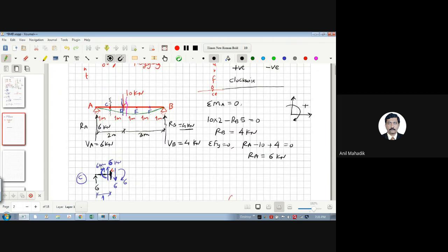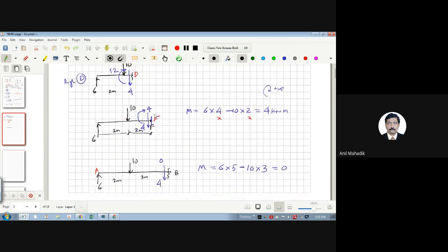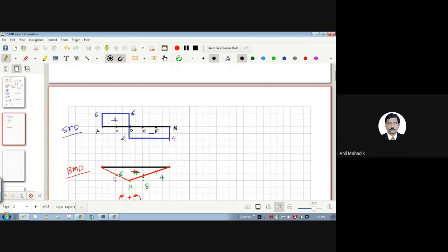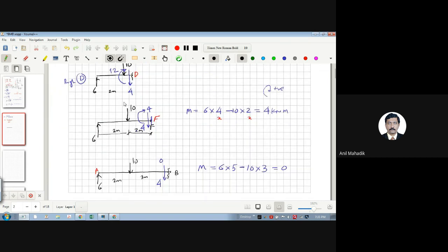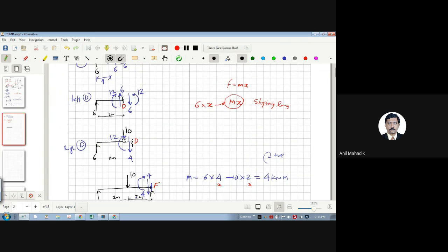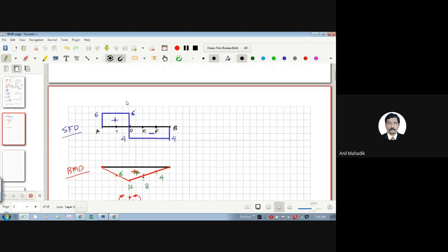Calculate the shear force and bending moment values there. Again take the next section. Always take the section at the point loads, always just to the left and just to the right. And in between you can take sections too, so that you get an idea how the line will develop. So whenever there is a point load, please take the section to the left and right of the point load, as I did here.